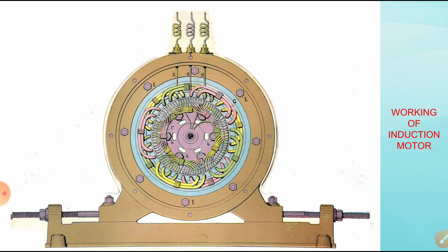They are maintenance free, unlike DC motors and synchronous motors, where the brushes, commutators and slip rings require a large amount of maintenance. In a squirrel cage motor there are no slip rings and brushes, hence it is maintenance free and rugged.